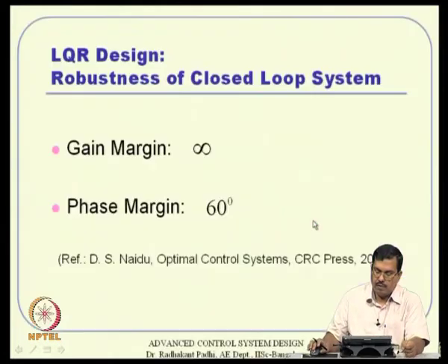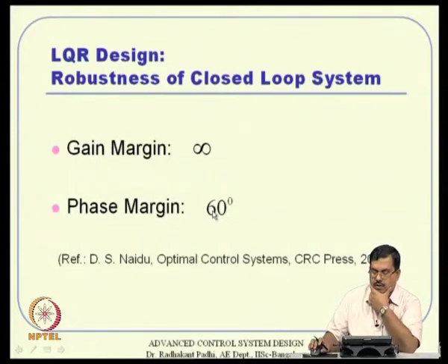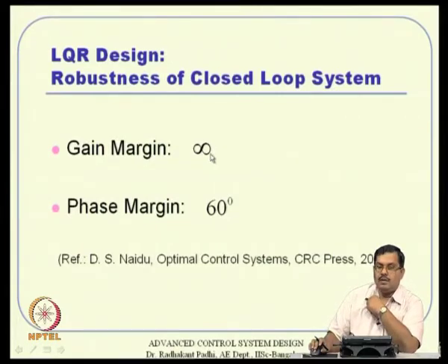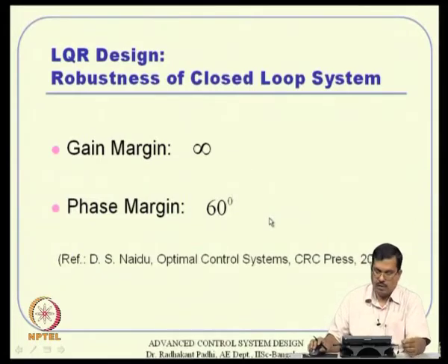Now, extensions of LQR, but okay, before I proceed further, also remember the moment the states are not fed back in exact sense, that means you consider this so called LQG design and all that, where the state needs to be estimated through an observer or filter, then these properties are lost actually. Okay, that is a major drawback, major hurdle actually, and that is why people talk about LQG/LTR design. That means that LQG design turns out to be LQR design with Kalman filter based state estimation, and then LTR is something called loop transfer recovery and all that actually. Okay, so, those are concepts that are available from the linear quadratic design details and all that. Those of you who are interested can see some appropriate book actually. One of that book is certainly this book actually, you can also see details of that here.